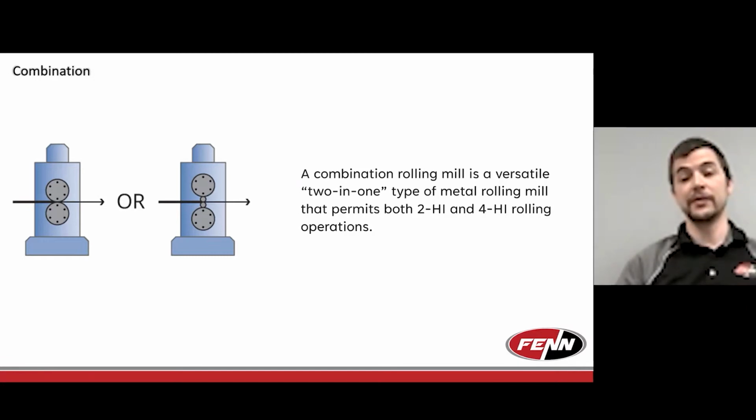The downside is because they're friction contact on the 4-high work rolls, they're a little more limited in how thin you can gauge versus a 4-high rolling mill that's specialized to only run for that purpose by having a direct drive. So for guys in the foil industry or things like that that are only rolling thin and are never doing anything beyond that, a 4-high work roll driven mill becomes ideal. For guys that oftentimes are doing stuff on the R&D side or production side where they might use the mill to take heavy reductions as well as gauge relatively thin but not extremely thin, a combination mill works well to cover them in that versatility.